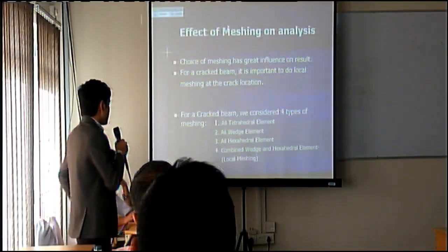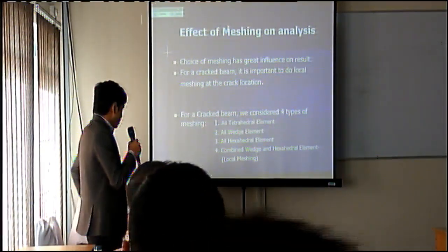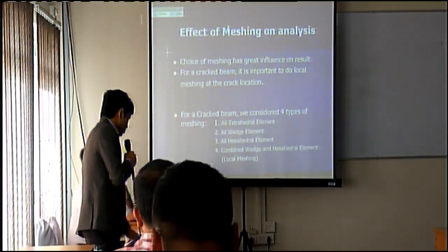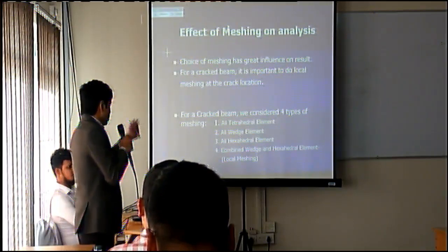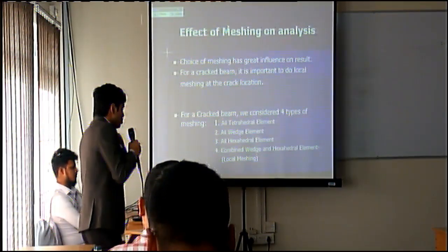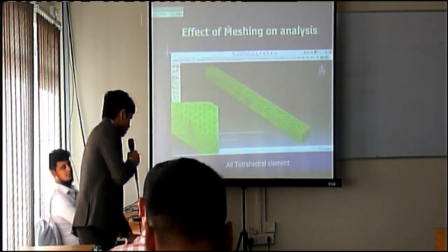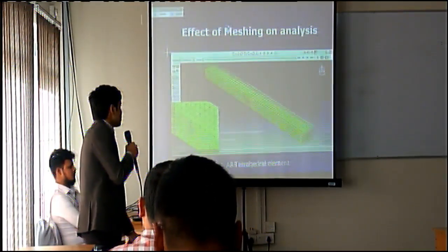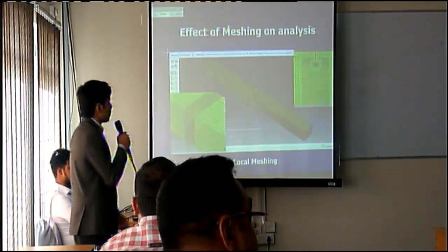Now the effect of meshing on analysis. If the crack is present, then the meshing is quite different because combined meshing is required. All tetrahedral, all wedge, all hexahedral and combined wedge and hexahedral elements were chosen for the selection of the meshing. Here the all tetrahedral element, all wedge element, all hexahedral element, and this is combined meshing.